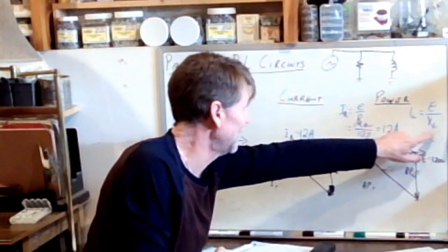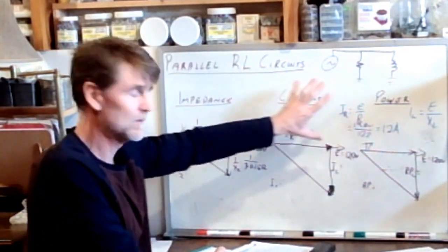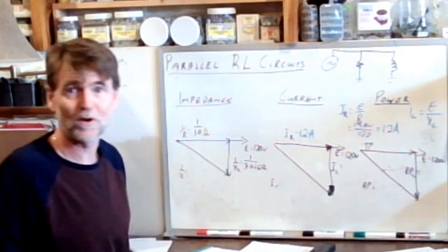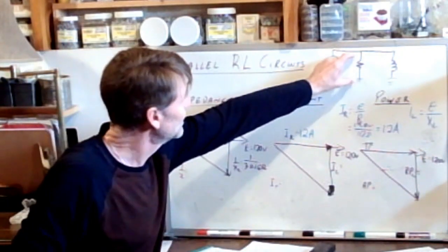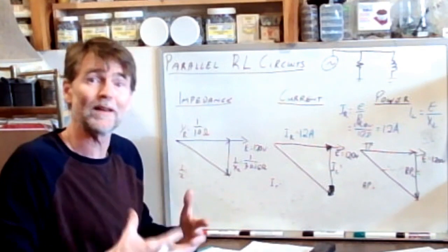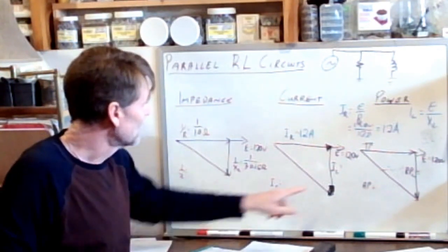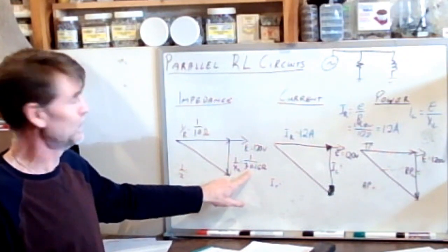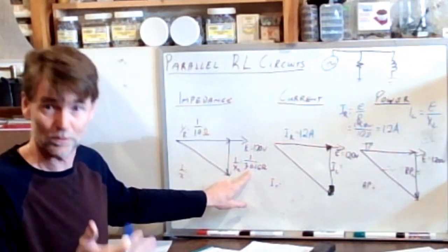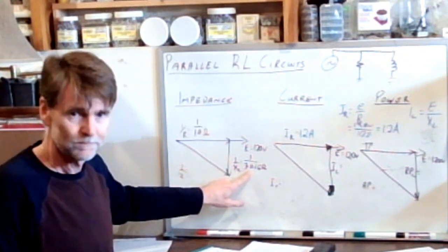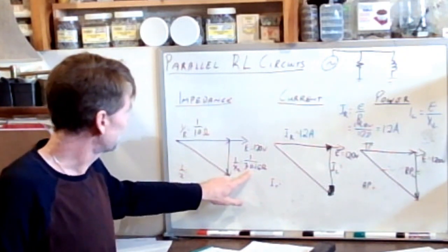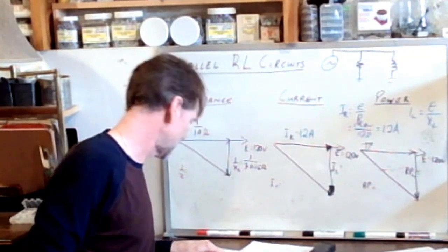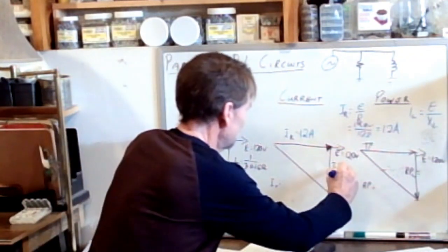We're just making sure we have all of the right variables so that we're talking about the same sides of the triangle or the same locations within the circuit so that we can apply Ohm's law. So still 120 volts. Now the value of impedance or resistance or reactance, so many different terms, 30.16 ohms, and that equals 3.98 amps.